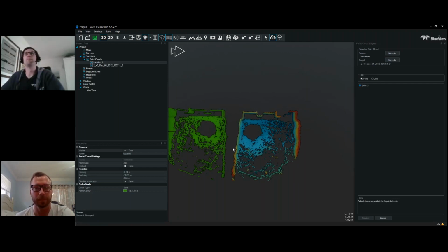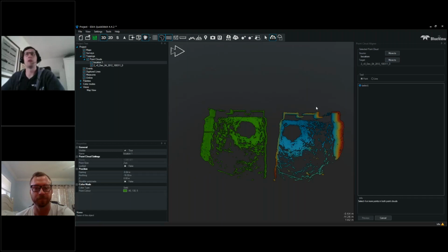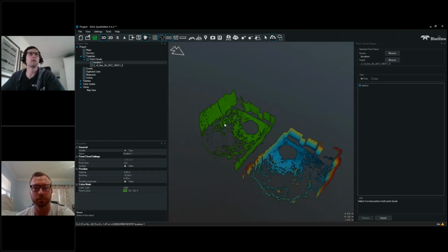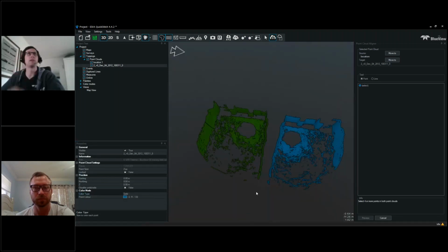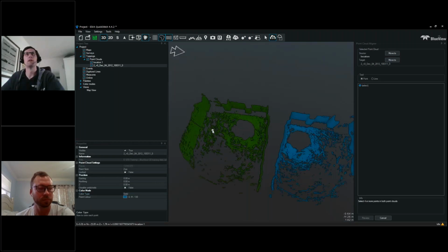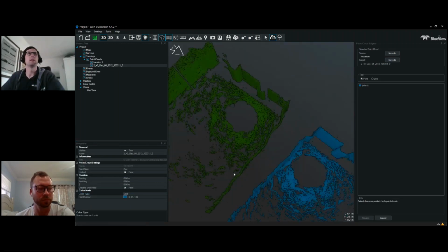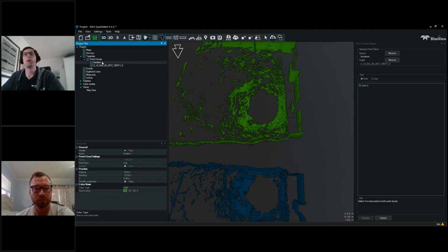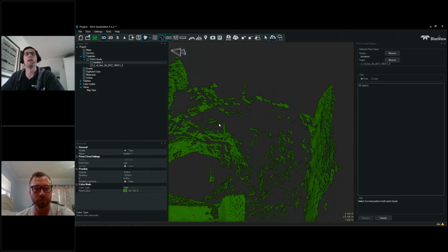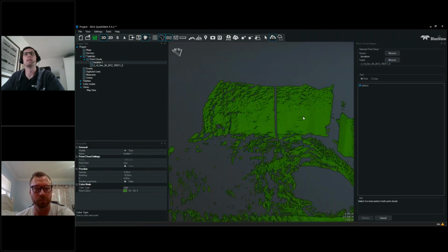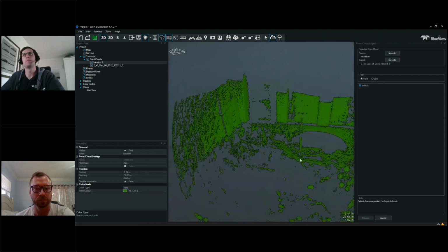So in Quick Stitch, there's a point and a line, so I can identify common points and common lines. First thing I like to do, let me make this another solid color, just so we have two point clouds in 2 different solid colors. First thing I like to do is look at one of the point clouds, see if I can find any features that I can easily use for registration.